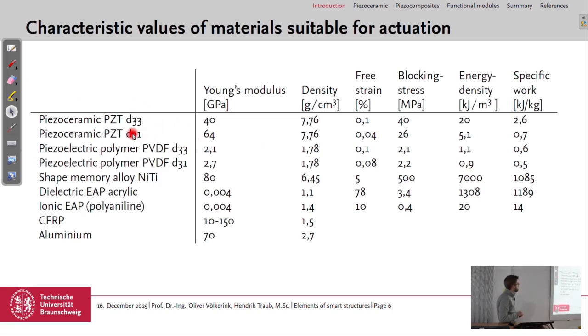Again, an overview of the different materials. Yesterday we had a look at piezoelectric polymers, for example PVDF, or the dielectric electroactive polymers and the ionic electroactive polymers, and using them as multifunctional materials which also have load-bearing properties. We can see here that the Young's modulus of these materials is quite low, and also the blocking stresses are quite low. So we'd like to use piezoceramics in combination with, for example, CFRP or aluminium to really use the multifunctionality of these materials.